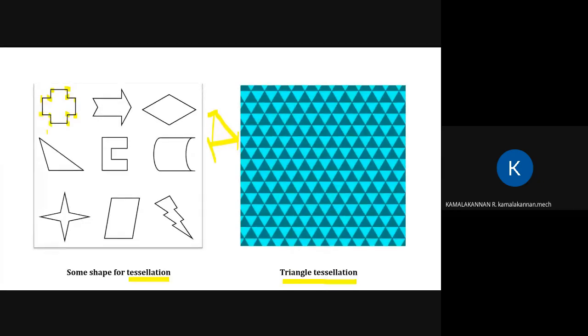With this shape you need to store 12 points. Finally, your data will be larger and transferring the file will be much tougher. When you take a star, there are 8 vertices. So when you choose a shape, it should be as easy as possible to store data while carrying more data about the geometry. That is why the STL file chose the triangle as its tessellation.